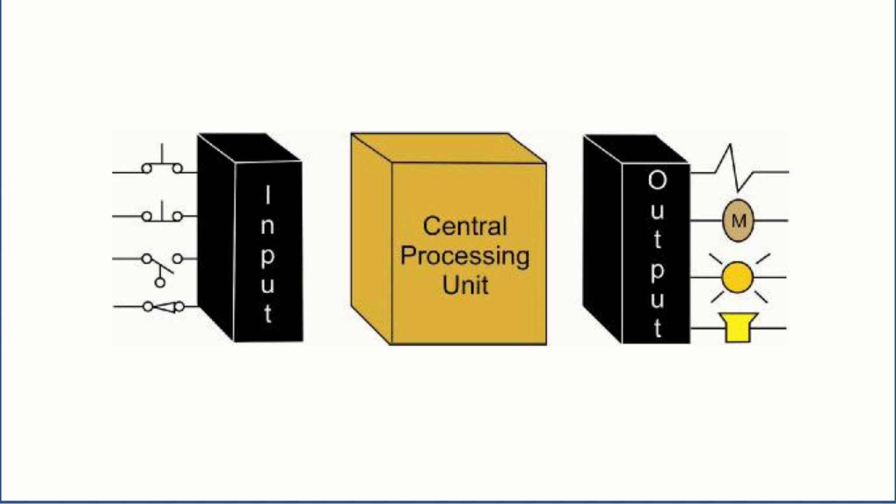Now let us make the situation a bit complex. Let us talk of not Coca-Cola but Sprite or a simple water bottle. Now you see that the laser is perhaps able to pass through a bottle filled with water or Sprite, because it's a transparent liquid. Now what will we do? You can see that the earlier sensor, which was perfect in determining whether the bottle is filled up with Coca-Cola, is not going to serve our purpose.